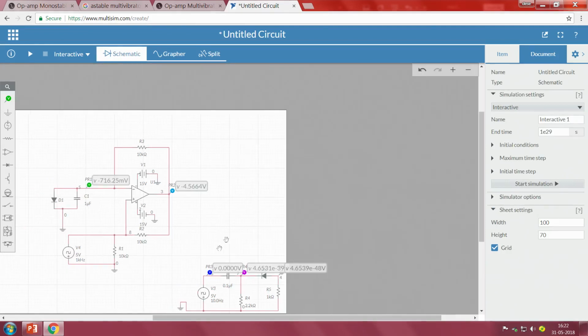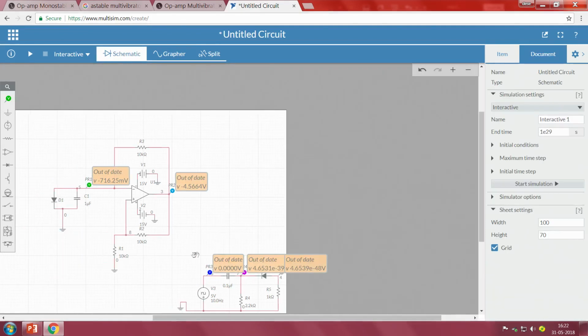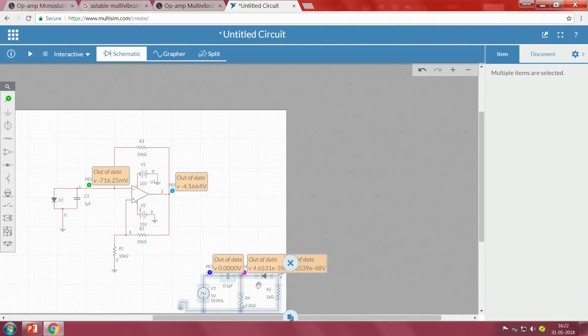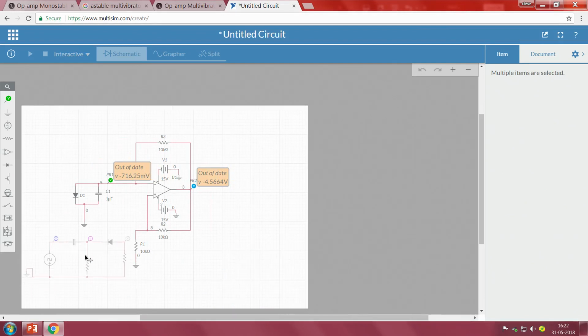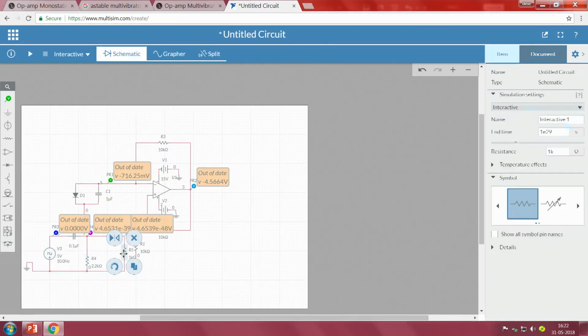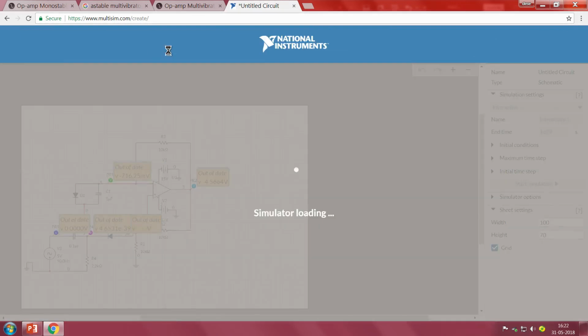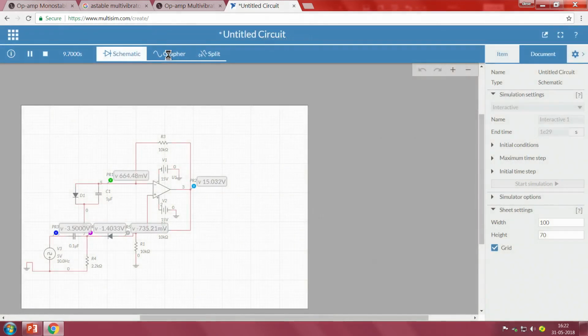Now, we will connect this particular circuit by replacing this with this. So, what we do is select this complete part and move it from here to here. Now, I already have a resistor, so I do not need this resistor here, this is just a load resistance, and this value has to be connected here. So, I am connecting it here.